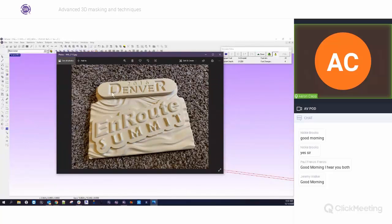Then he did something very similar to what we did: he used an island fill with a 3D engrave to cut out these letters. And then down here, he did the opposite. Instead of using a 3D engrave, he used the pyramid tool in order to get these letters. Obviously, you need to make sure that you place your toolpaths in the right order. So when he milled out this edge here, he also had to create a mask for these little letters, because you wouldn't want to knock out that whole section of letters.